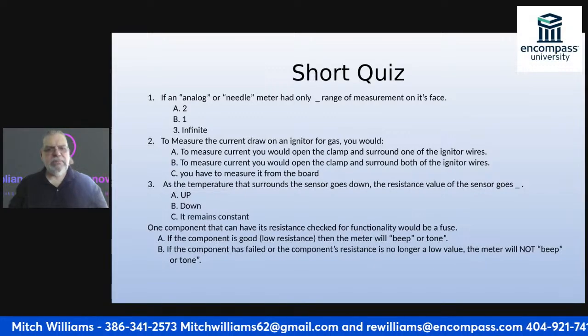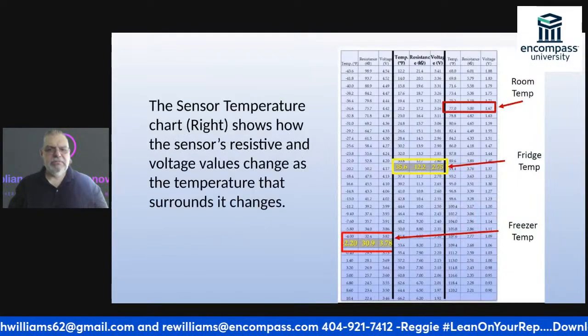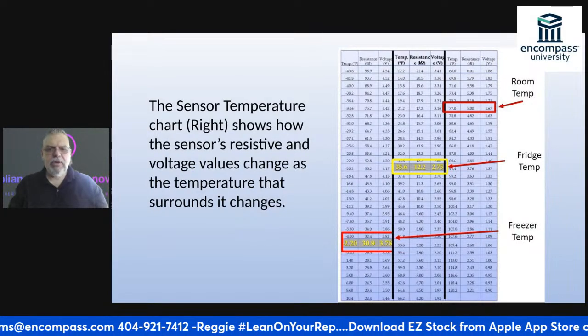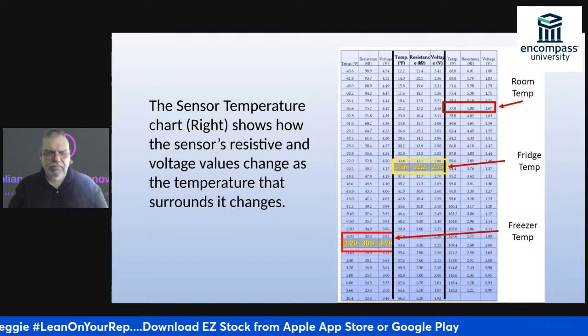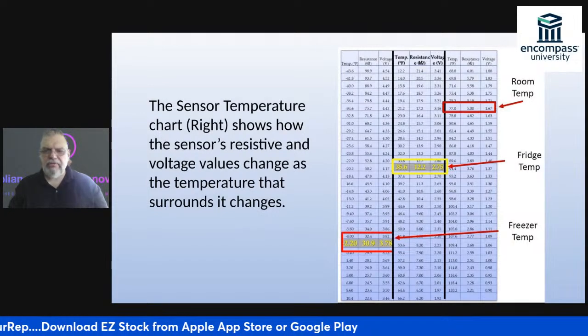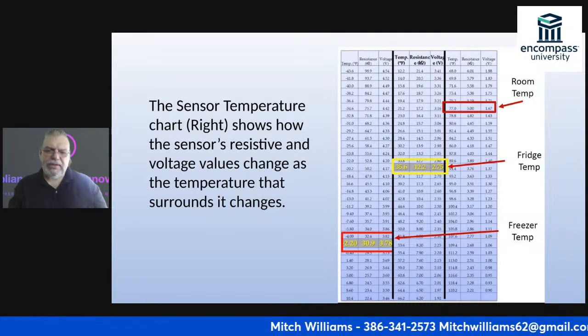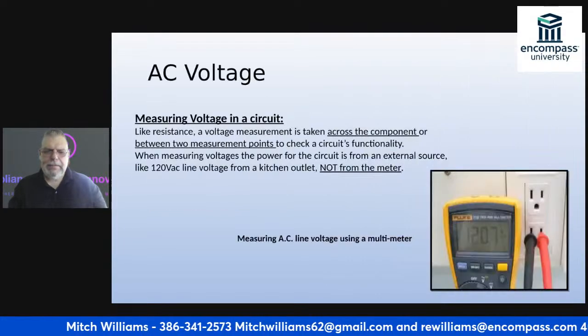Okay. Once again, I'm going to do it one more time. Somebody give me an answer. Okay. If my temperature goes down, my resistance goes up. Look there, 35.6 degrees. The resistance is 12.2. If my temperature drops to 2.2, my resistance is now up to 30.9.